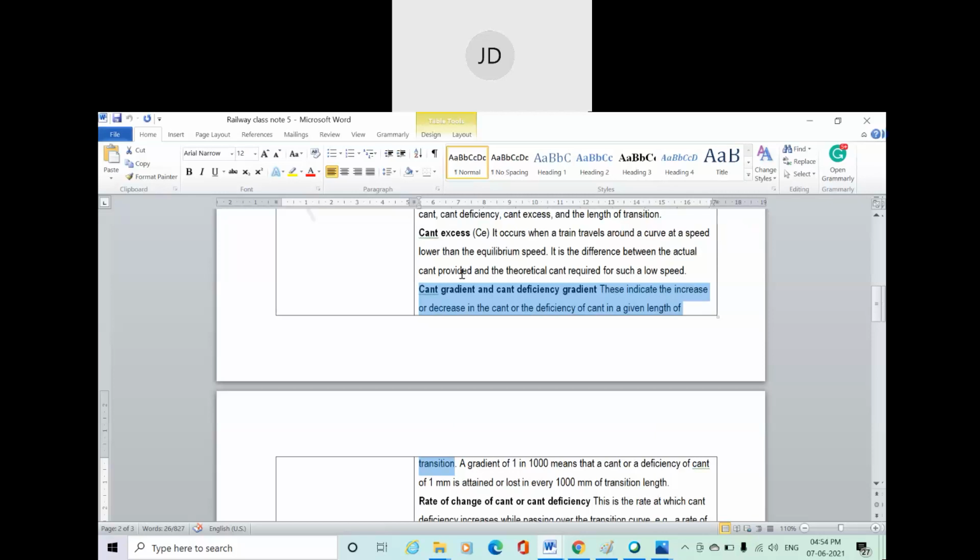Now, this superelevation is also introduced in the transition curve itself, but it is gradually increasing. If I show you a simple diagram, suppose this is a straight track. At a particular point, the maximum superelevation should be up to this. Now there is a gradual increase of superelevation. From the straight track, we need to go to a transition curve.